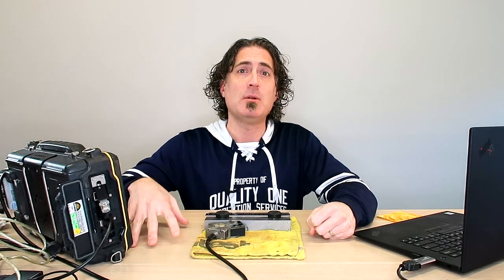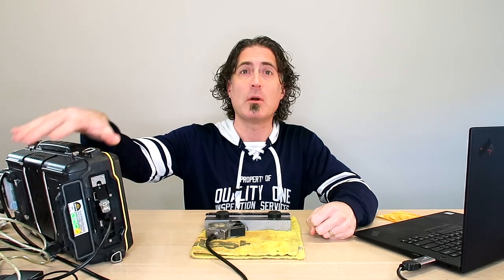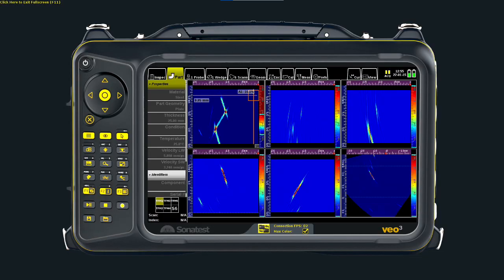Now, intermodal or multimode TFM is not entirely new. It has been available on some software packages in the past, but this is the first time that it's been made available on a field portable instrument. We can combine up to 4 modes at once in real time. You can do that in combination with regular phased array or regular TFM. For the purposes of this, I'm just going to use 2T, 3T, 4T, and 5T for all these demonstrations.